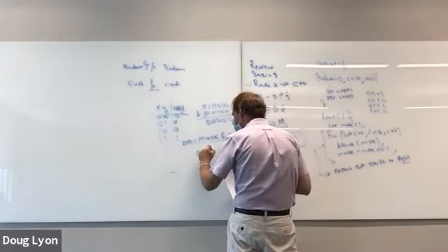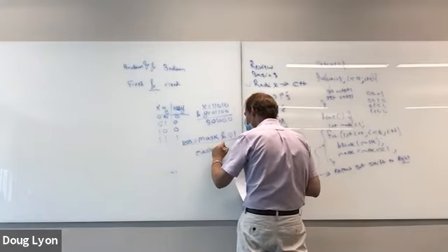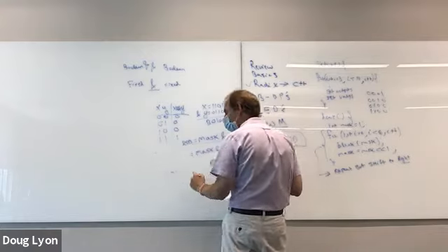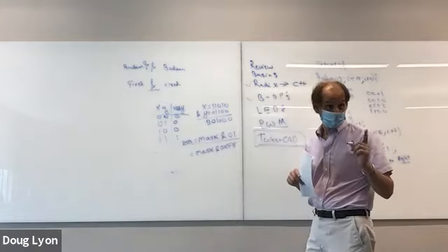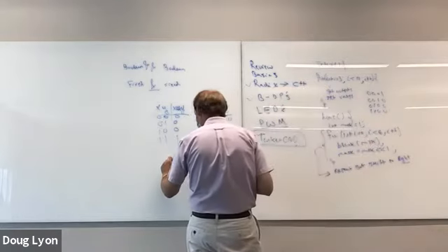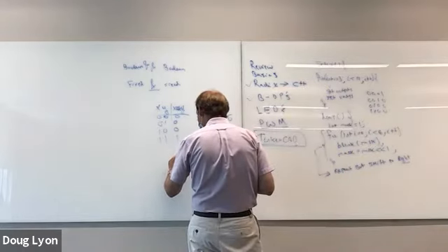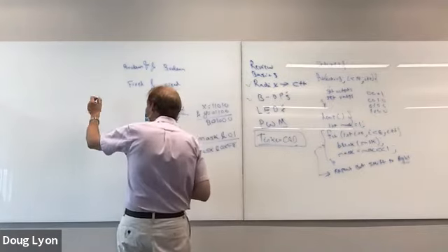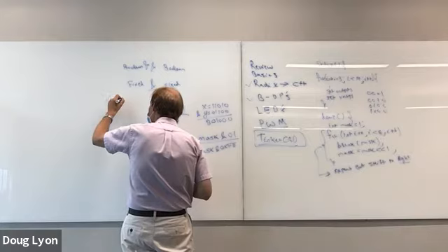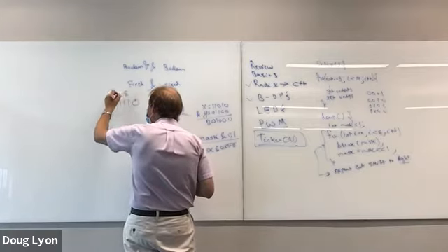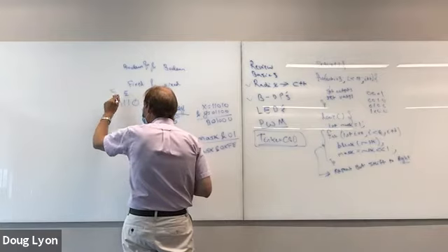Mask ampersand 0xFE will isolate the most significant 7 bits. So you asked a very good question there. So this is the most significant 7 bits. Why? Because what happens when you have a mask that looks like this? 1, 2, 3, 4, 5, 6, 7, 0. That's going to be FE if you group by 4.